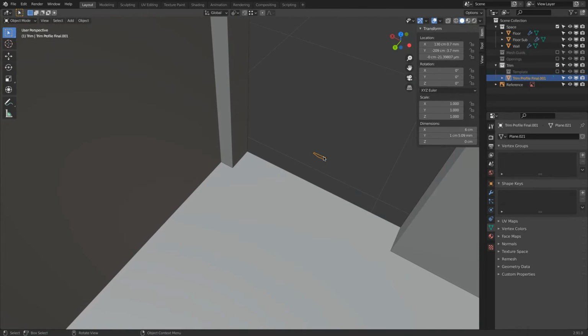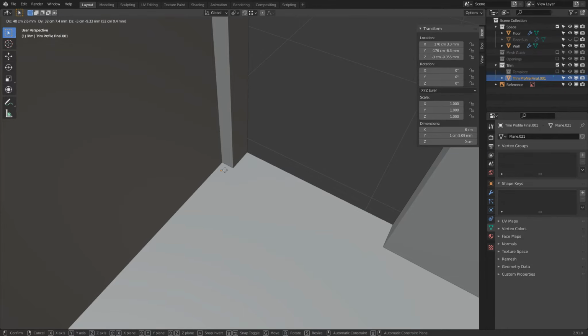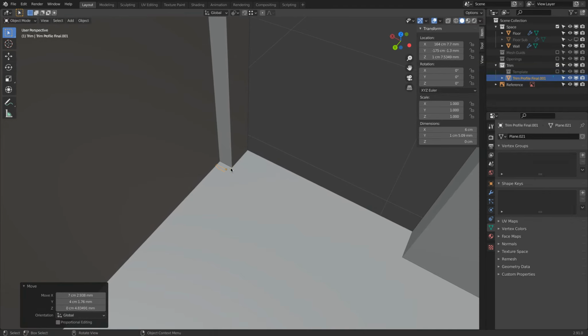So this I would like to put along my door frame. So this will actually go along this opening and sit on, well, it's based on how we do this. If this is hardwood floor, it sits on the hardwood floor. If it's carpet, it actually sits on the subfloor. We have hardwood floor, so we put this on top of the object. So I want to snap this to the edge of my actual floor. So the subfloor I turn off just to make this easier to see. Yeah, so the snapping was not good. Now it's better.